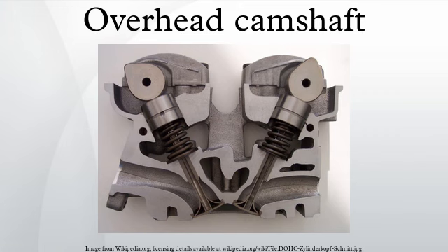In conjunction with multiple valves per cylinder, many OHC engines today employ variable valve timing to improve efficiency and power. OHC also inherently allows for greater engine speeds over comparable cam and block designs, as a result of having lower valvetrain mass. Fundamental types of OHC: there are two fundamental types of overhead camshaft layout, single overhead camshaft, and double overhead camshaft.